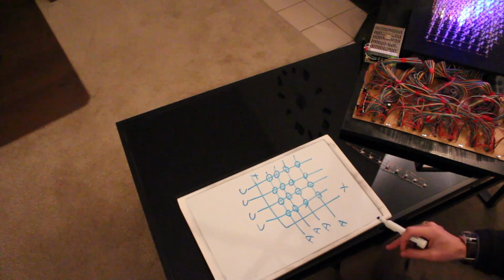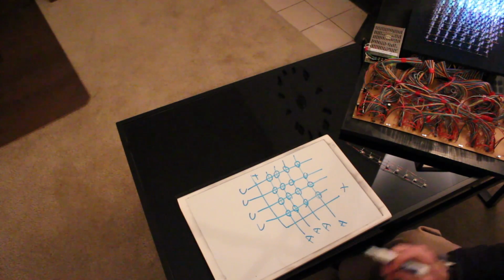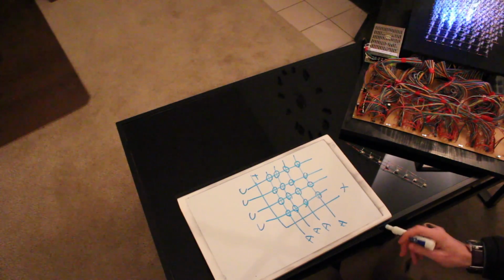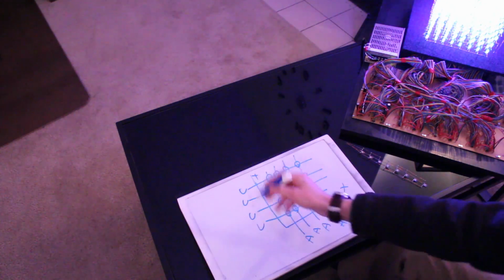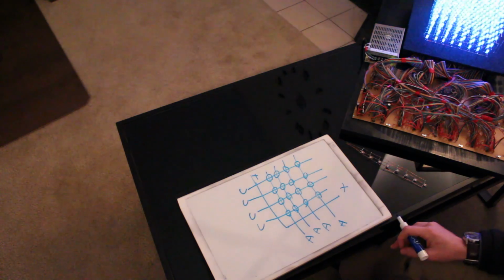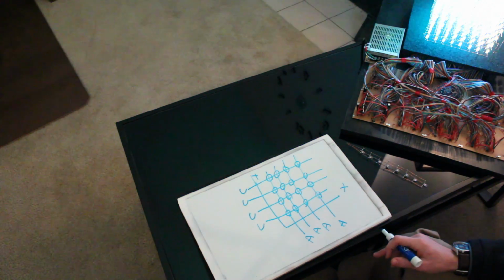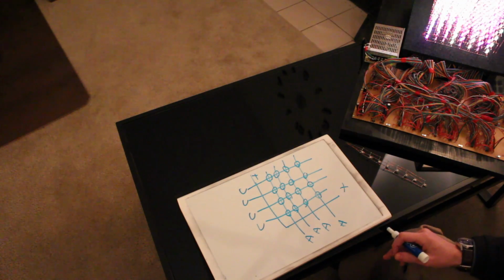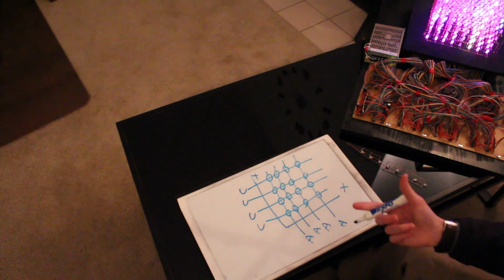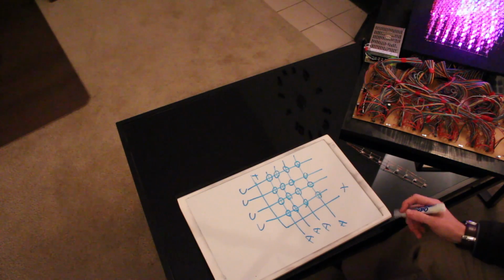It's not really the most efficient thing in the world, but hey, you could control all of this via one 8-bit shift register, okay? Because it's 8 bits, so you get 8 outputs. And we'll talk about shift registers in a second. So that would mean you'd only need 3 pins off your microcontroller, a clock, data, and a latch, to control 16 LEDs.